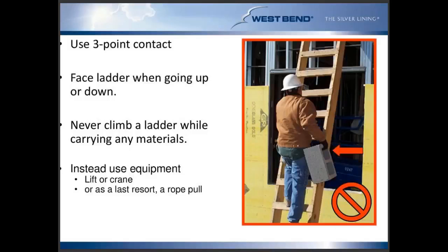And instead of using his hand to carry the cinder block up the ladder or down the ladder, we want to look, is there equipment that can be used? Oftentimes, especially in a construction setting, there is going to be some sort of lift, whether it be a telehandler, a crane, something that can reach that roof or upper landing surface and take that type of material or equipment to that area safely, as opposed to somebody climbing a ladder.